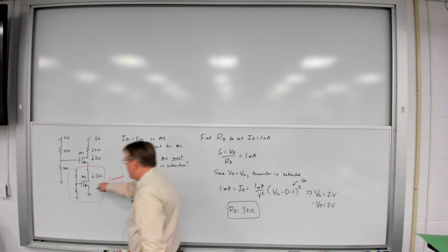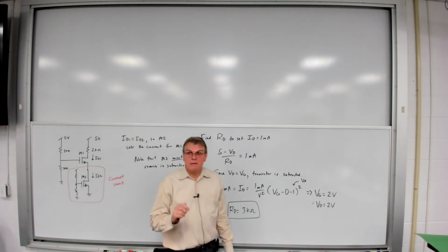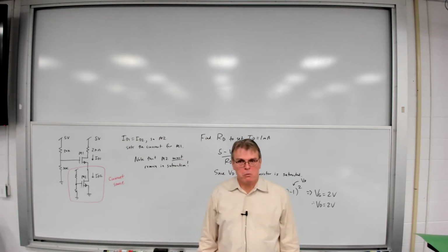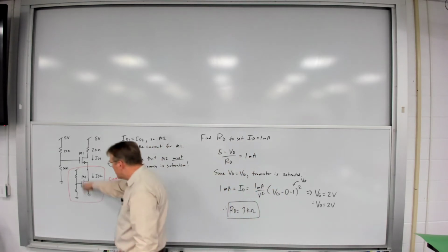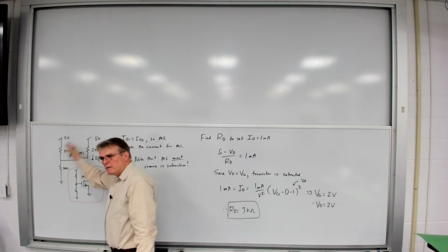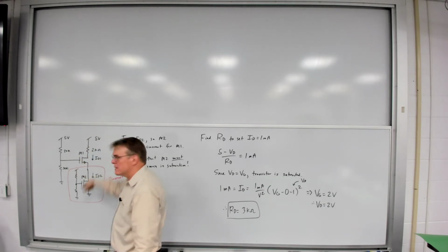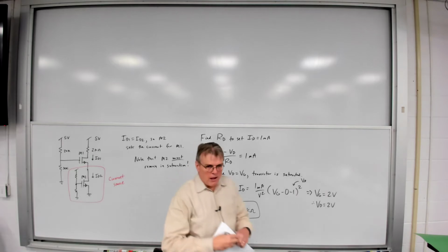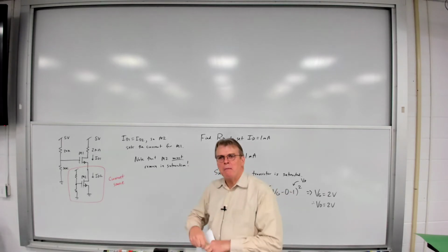So a second transistor actually gives us now a very stable bias point. All we really have to do now is focus just on making this stable, and the rest of the circuit, we're fine, because this is going to set the drain current. There's only one tiny problem with this circuit.